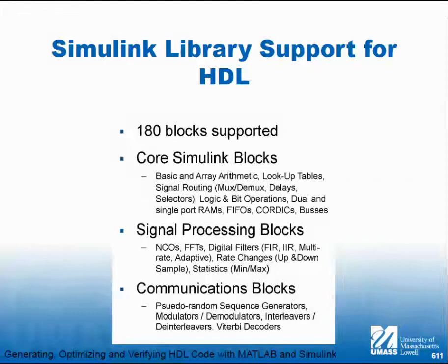It has signal processing blocks, so all your favorites, FFTs, finite impulse response filters. A note here, this is kind of what I do all the time. If you use the Xilinx tool, something like Vivado, Vivado has a library of signal processing elements, and you can design them at a high level.